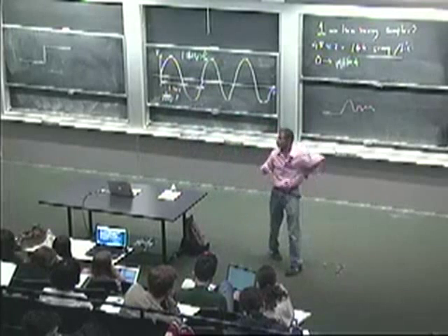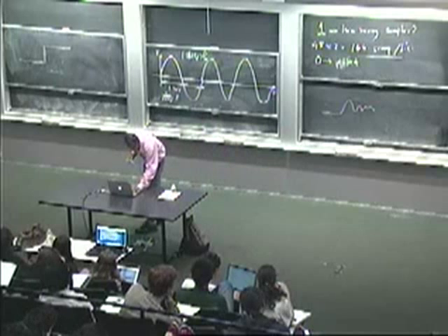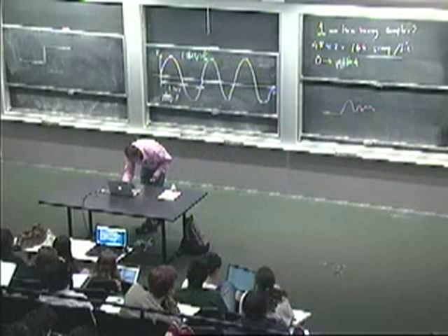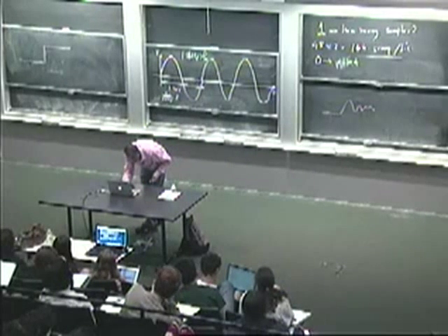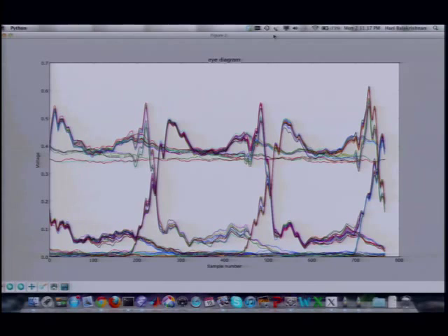So the eye diagram is a way to capture that. What the eye diagram does is it's a kind of clever hack. The way you generate an eye diagram, you don't have to worry about writing the software for it, but you will look at a lot of these kinds of pictures in Lab 5. You transmit a random sequence of bits. And then you look at the samples that were received at the receiver after the demodulation was done.